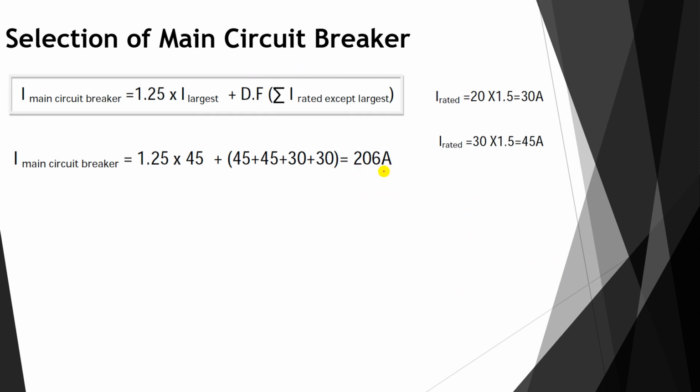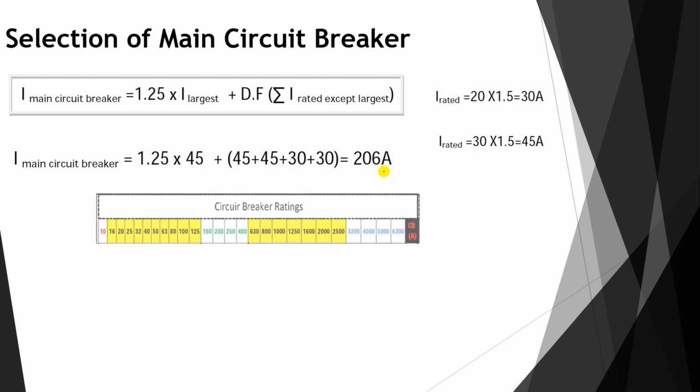Okay, so how can we get the cable again? Similar as before. Before this, again, we need to find the circuit breaker suitable for this application. So 206 ampere, if you look here, we have 160, which is very far and low, then 206. We have 200 ampere or 250. 250 is larger, so as you can see, 206 is between 250 and 200.